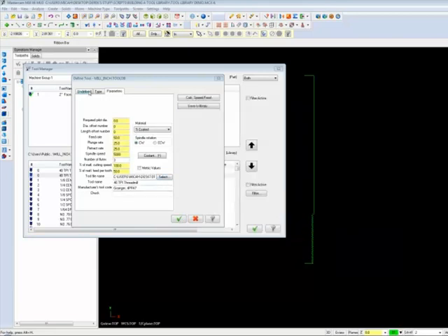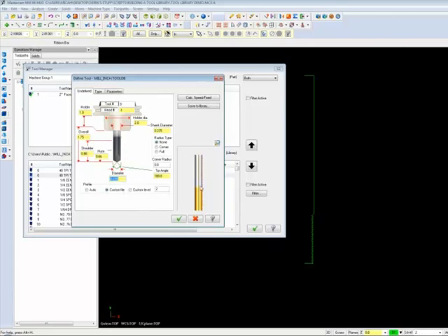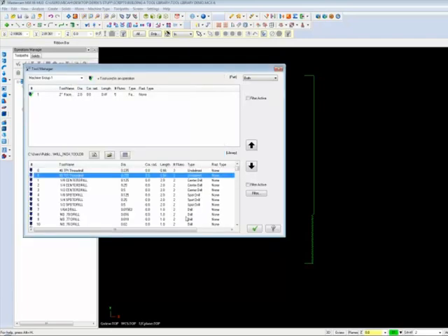So now let's go to the undefined. Now you see there's your profile. Cool, and I picked that out based on whatever geometry was in the file. Correct. So now when you say OK and save that, it'll be in your library. When you save it to your library, this geometry is associated to it. So of course you want to put a copy of this into your standard tools, where all the Mastercam tools are for mill.